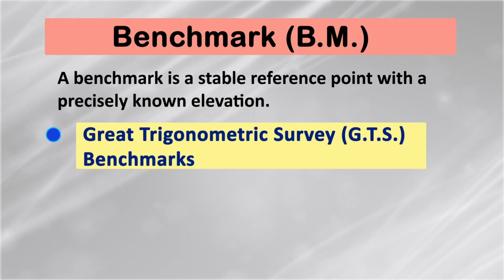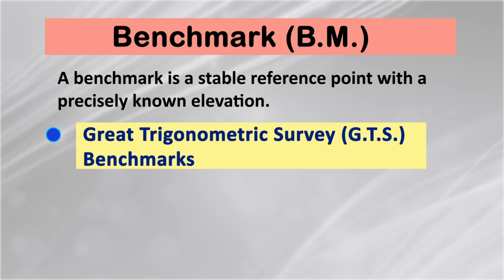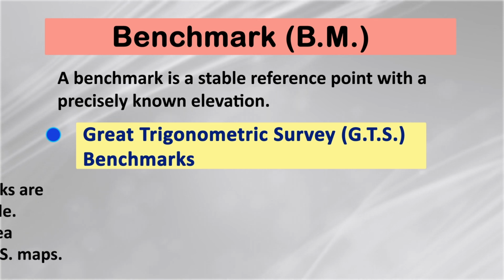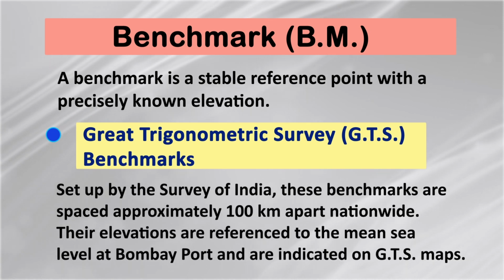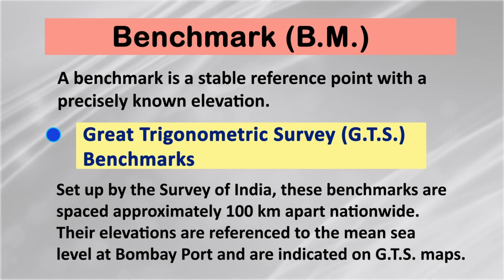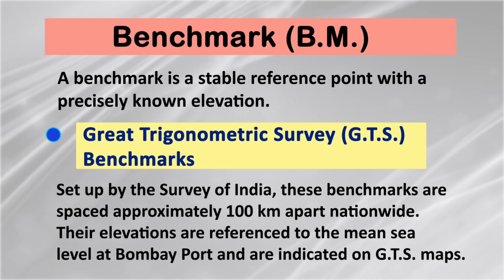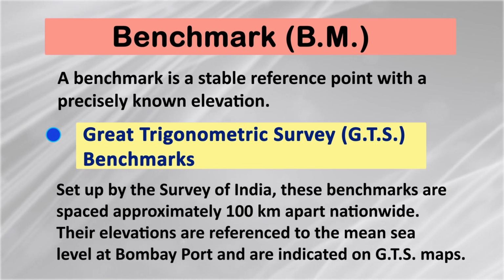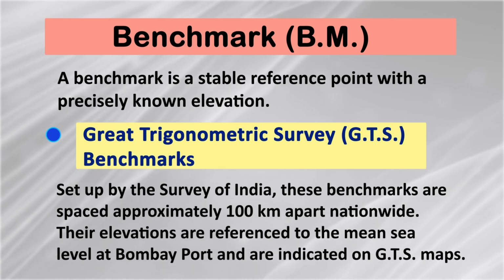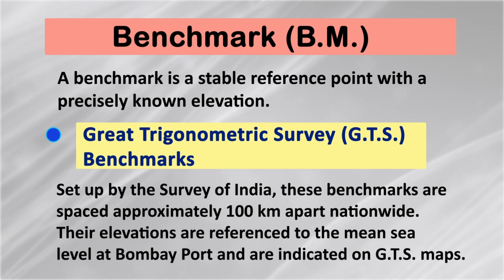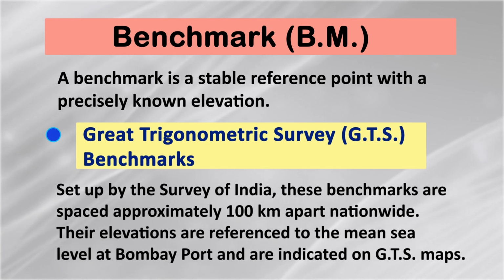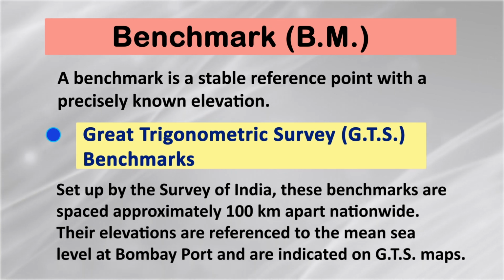First is Great Trigonometric Survey, that is GTS benchmarks. These are set up by the Survey of India. These benchmarks are spaced approximately 100 km apart nationwide. Their elevations are referenced to the mean sea level at the Bombay port and are indicated on GTS maps.